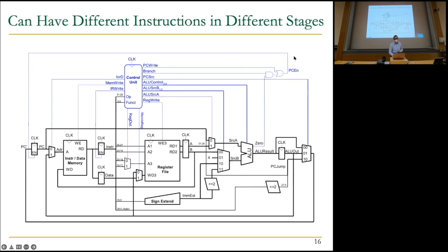So what we're going to try to do is, when the blue instruction is writing its results, we're going to have another instruction, a yellow instruction, doing address calculation or doing something in the ALU, another instruction in the decode stage, another instruction in the fetch stage. Here, I don't exactly show the memory access. I have 4 over here, but we'll do 5, as you will see soon, because it was not as easy to color the memory access stage, because there's a single memory, as you can see over here. So we're going to change that with pipeline. So that's the basic idea.